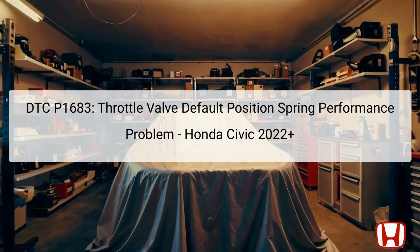The diagnostic trouble code DTC P1683 indicates a problem with the throttle valve's spring performance in the Honda Civic 2022. The throttle valve is crucial in managing the air entering the engine, which significantly affects the vehicle's performance. If the throttle valve does not achieve its designated position, this can trigger the powertrain control module (PCM) to register an error, thus storing the P1683 code.